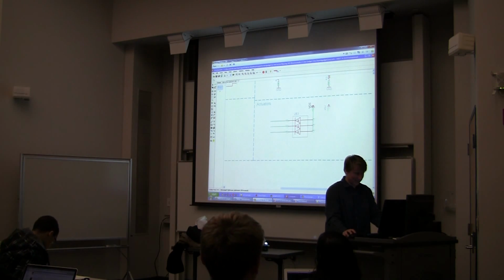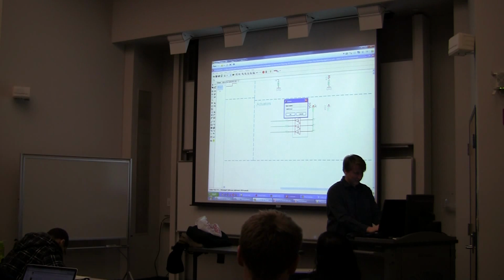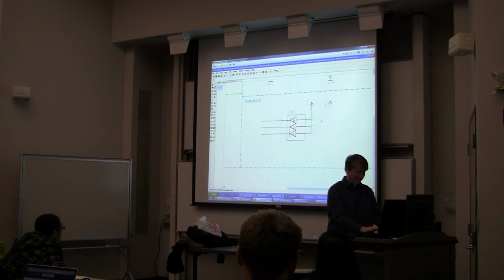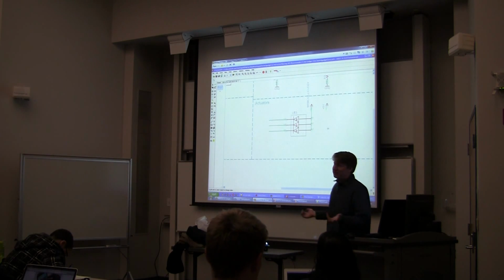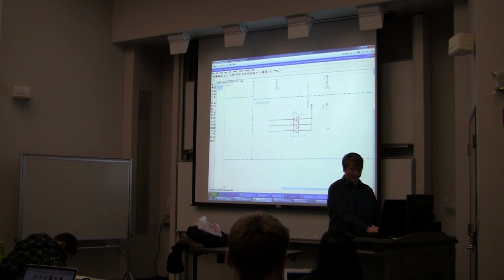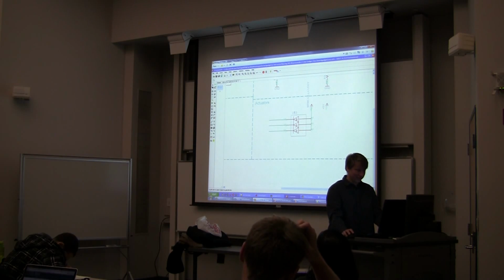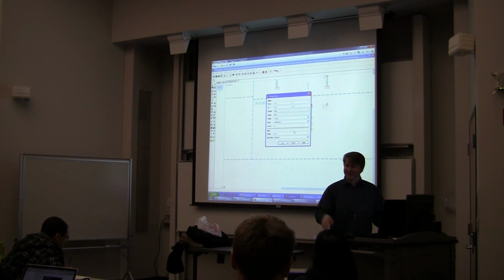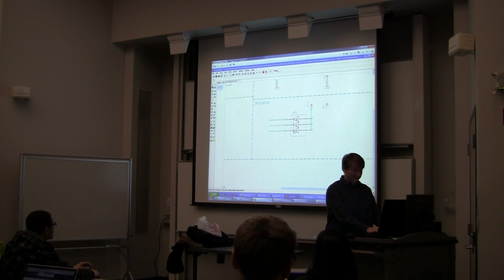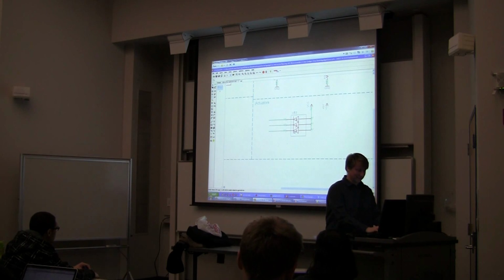Like I could name this Mr. McGillicuddy, but that doesn't actually change anything. I could change this to Mr. McGillicuddy. That's hard to say. So now I've got that. Is that my new logic voltage? Maybe. It could be if you want to be consistent. But the thing is, it doesn't rename the trace. That's still called VCC. So you can't just rename those things and think that something good is going to happen. You'd want to use the plus 5 volt, or you'd have to go through and name them all randomly.